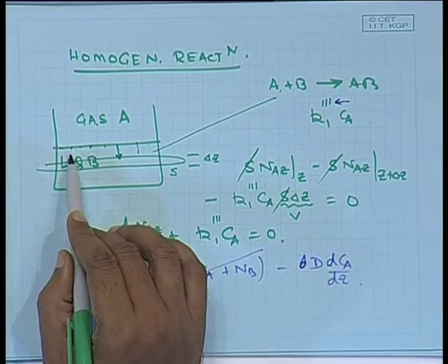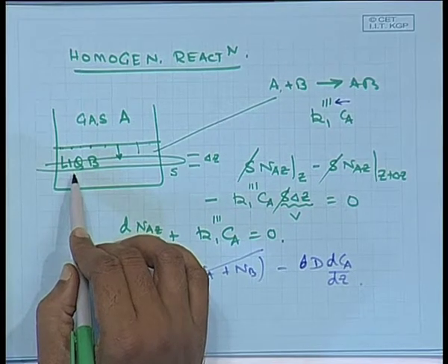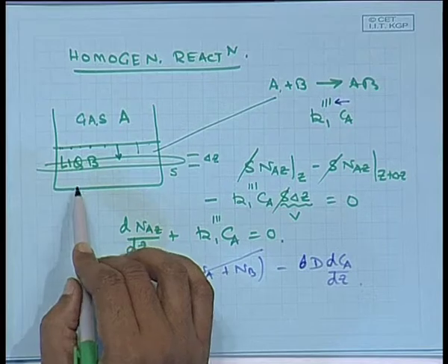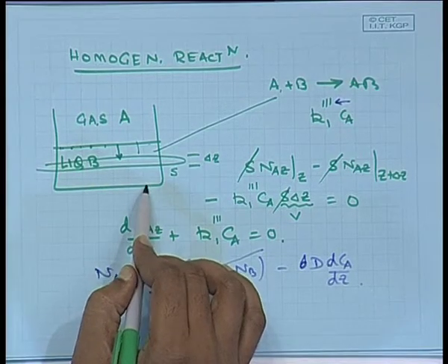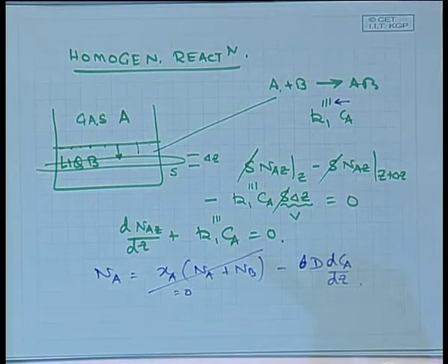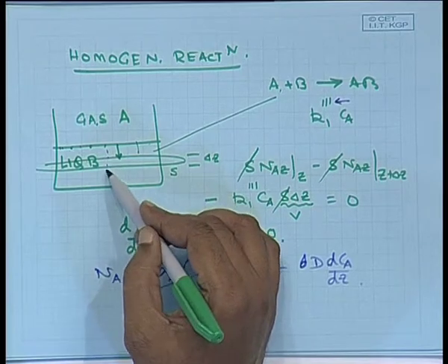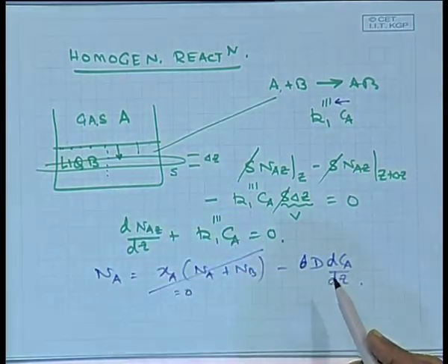If the rate of absorption is very small, then the molecules which are getting absorbed will not be able to move very fast, thereby not causing any bulk flow of B in the liquid as such. So, for a sparingly soluble gas, the amount of flow imposed by the diffusing A molecules will be extremely small.